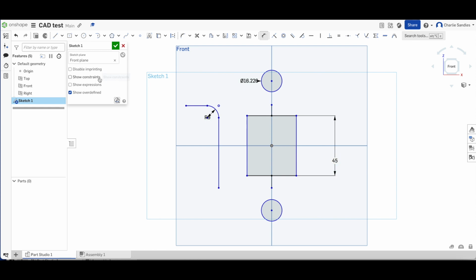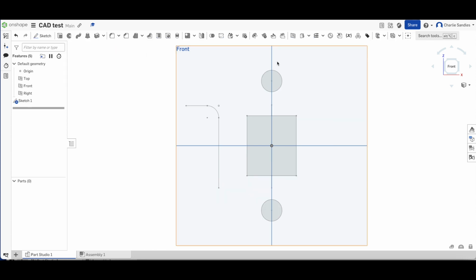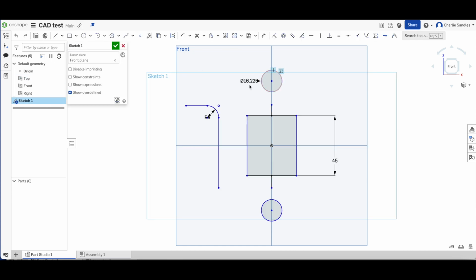Once I want to complete a sketch and I've decided that I've got all of the components that I want within my sketch, at that point I will select and tick out my sketch 1 box, and you'll see that that will complete that sketch. It's very common for students to think that after every single thing that you draw, that you press the green tick because you finish that shape, but we don't want to press this until we've fully finished whatever component we've been drawing on our interface, okay?